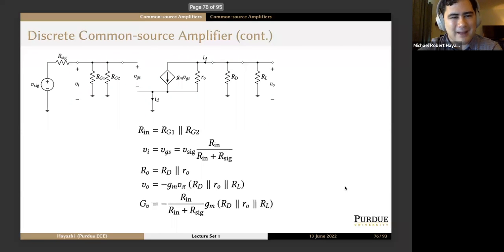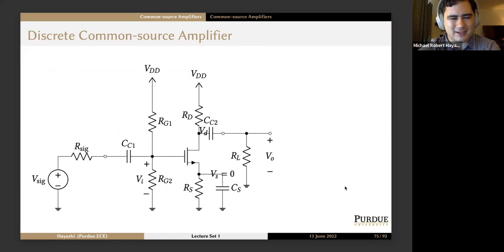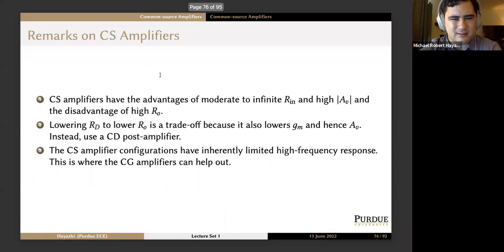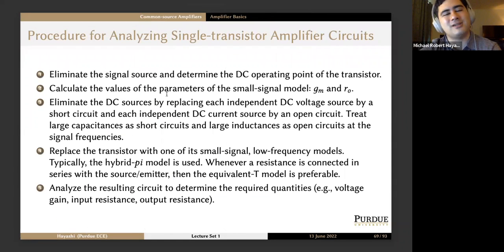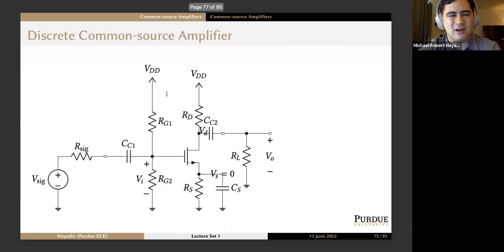Next, what happens if we do the small signal equivalent circuit? Okay, let's remember our steps. We do our DC analysis. Basically, you'd only need to analyze the middle portion of the circuit, which is a 4-resistor biasing network. Everything else only appears in AC, so those would be off. And then we do our steps. Step 2 was calculate the parameters of our model. So from this, we could find gm and RO. Bear with me. Step 3 is actually helping us construct our small signal model.